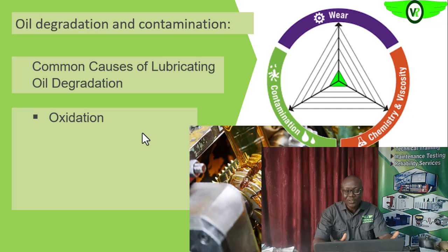And as this sludge forms, it increases the contamination level of the lube oil, and that can cause the blockage of filters and strainers, and also cause the seizing of mating parts, because the sludge can lodge in the space between those mating parts and increase the forces that the mating parts will need to overcome before they will turn.